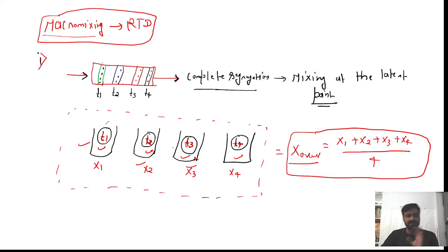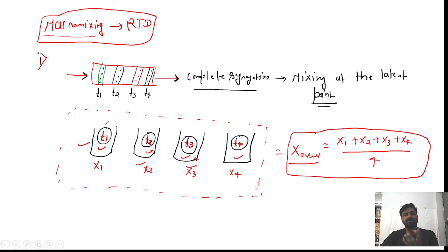Okay, up to this I think everything is clear how we are demonstrating the thing. Now, when we talk about the segregation model, because here I have discussed these things on the basis of mathematics, but what will we actually do from the perspective of chemical reaction engineering? So here you can understand the thing, that is the average conversion. If you have residence time data, if you have an RTD plot, it's very important.